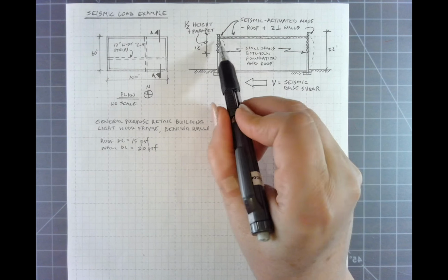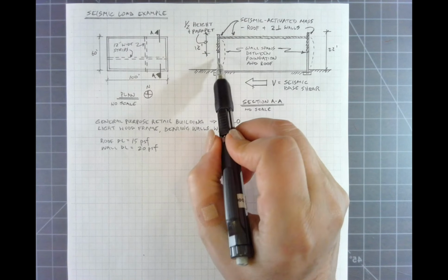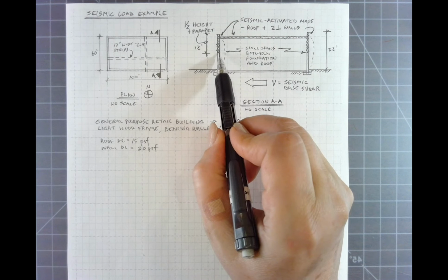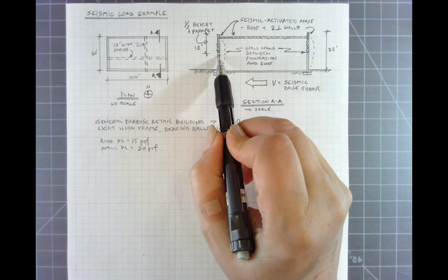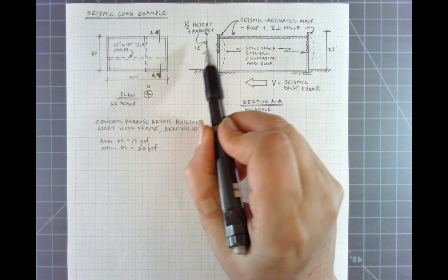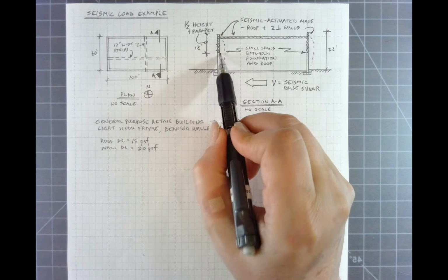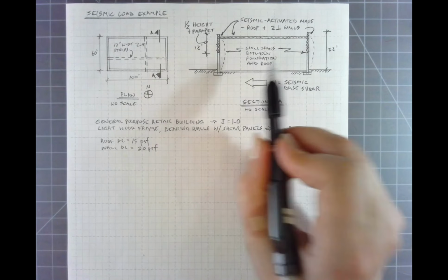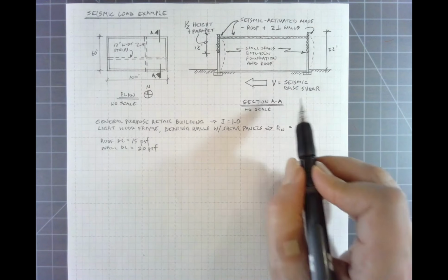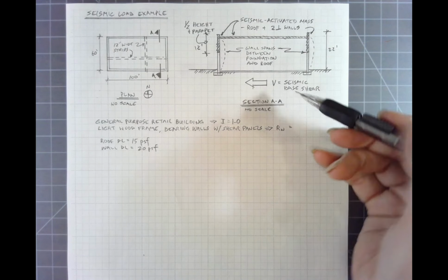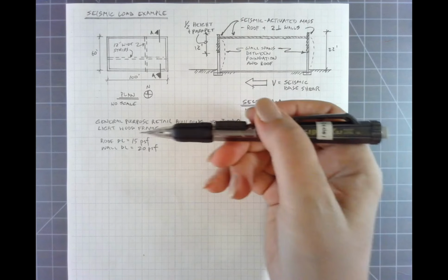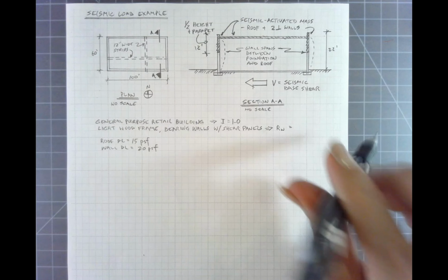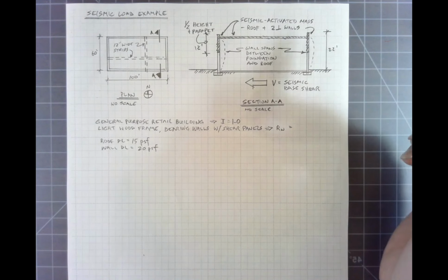So half of that weight, which in this case is half between the roof and the mid-height of the wall, so that's 10 feet, plus the additional 2 feet, that gives us 12 feet, so half of the height plus the parapet. And there's two of those, so we have to calculate both these together. So we're going to look at the weight of all of that. And again, this is looking at seismic shear going from the right to the left. It's cyclic, it will change its direction, and the walls have to go in both directions.